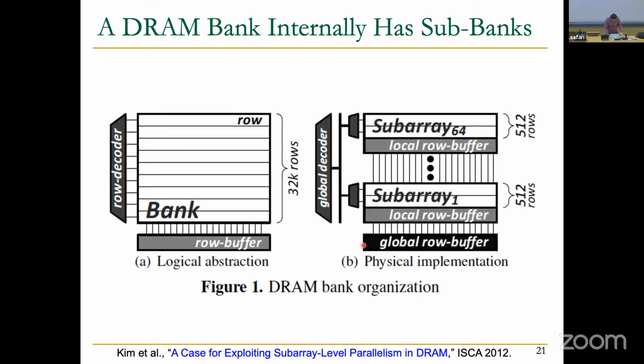Yeah, we've covered this. What's inside a bank? We won't look at DRAM operation at this much detail, but we will look at how it's organized further. You have what's called subarrays, or also named subbanks, inside a bank. You're partitioning your array further and further, basically. This left picture here is from the perspective of the memory controller. This is a logical abstraction of a bank. And the right picture shows you what it actually looks like.